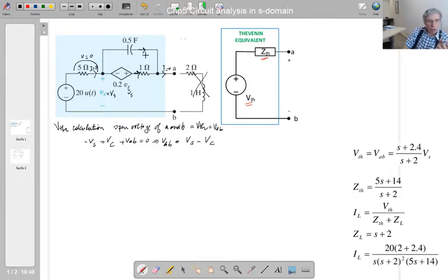So let me write now the Kirchhoff voltage law equation for this loop. Assume that the loop direction is like that. So plus Vc minus VR, this resistor voltage. Let's say we make it 1 ohm, maybe it is easier to see.